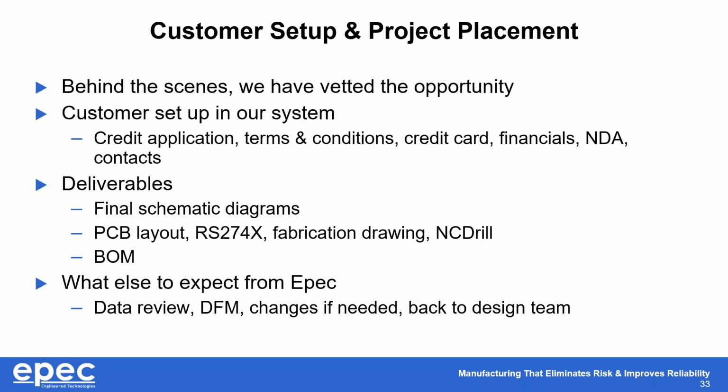And there may be some back and forth between us and layout and routing to make a change, pull some copper back, tweak some layer information, come up with a better layout for a specific reason where we have no room to do that etch compensation. In working directly with the design team, we perfect the data to go to production without having to worry about manufacturability.